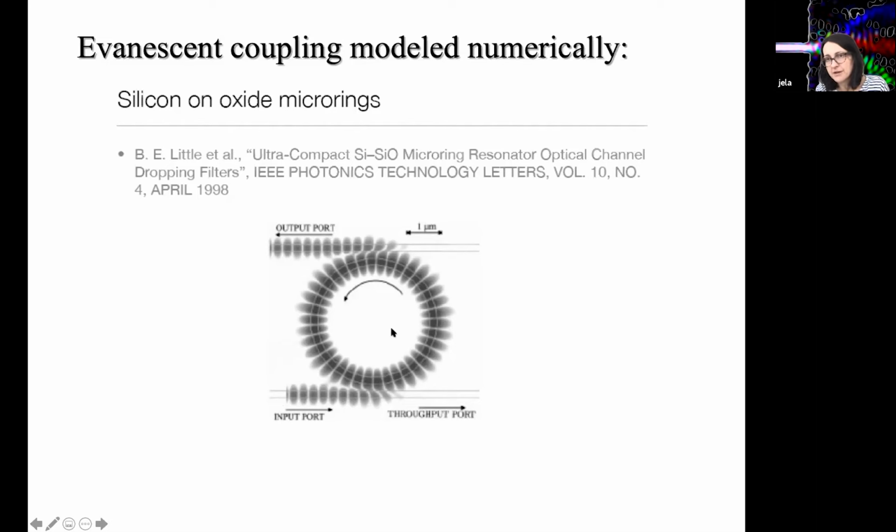Propagating modes are better, right? e to the i(m phi minus omega t). So you have clockwise and counterclockwise. So my forward traveling field on the input port actually here excites the counterclockwise mode, right? It's not going to excite the clockwise mode. And then I also designed the system so that this counterclockwise mode is dropped completely at the output port.